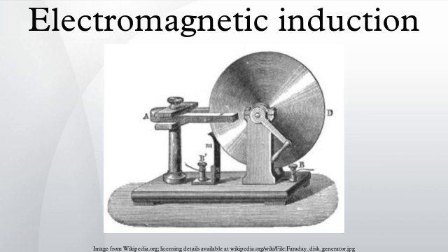Note the uneven distribution of the lines of force across the bar inductor. The magnetic field is more concentrated and thus stronger on the left edge of the copper bar, while the field is weaker on the right edge. Since the two edges of the bar move with the same velocity, this difference in field strength across the bar creates whirls or current eddies within the copper bar.